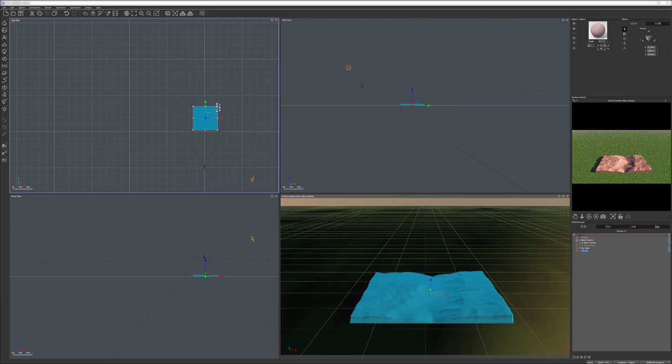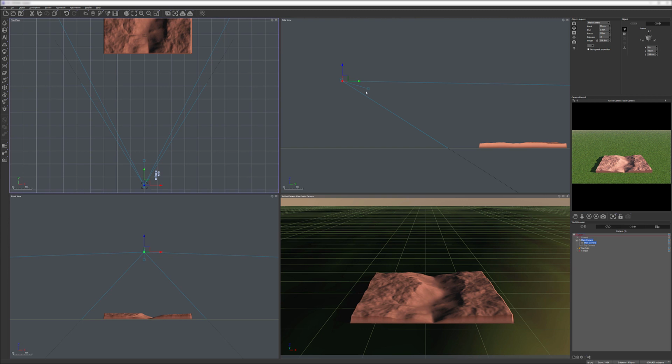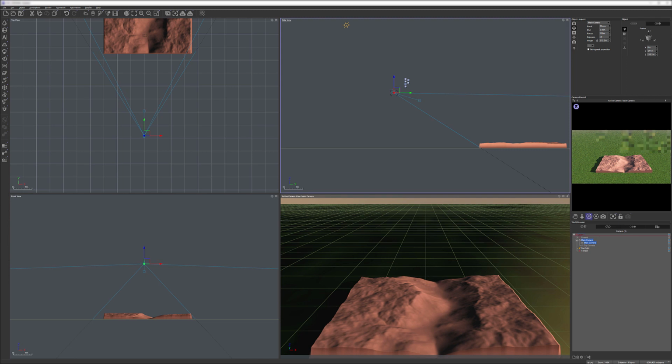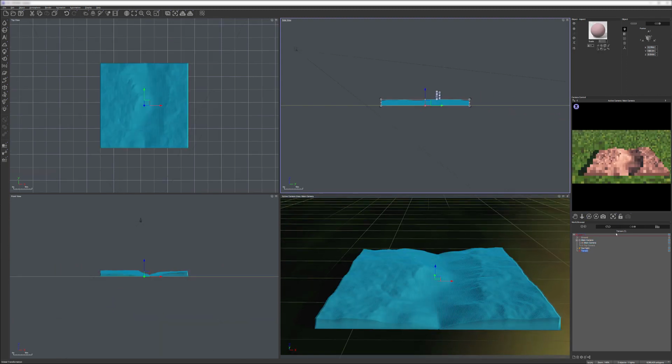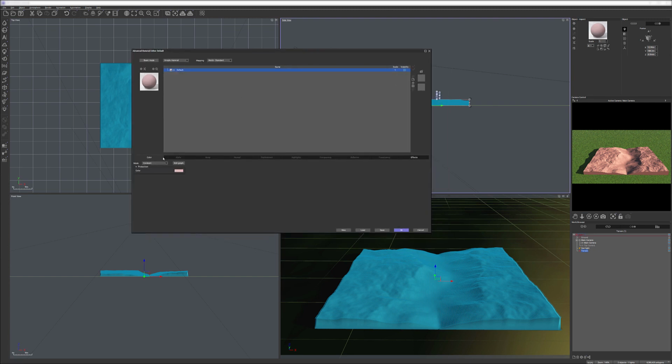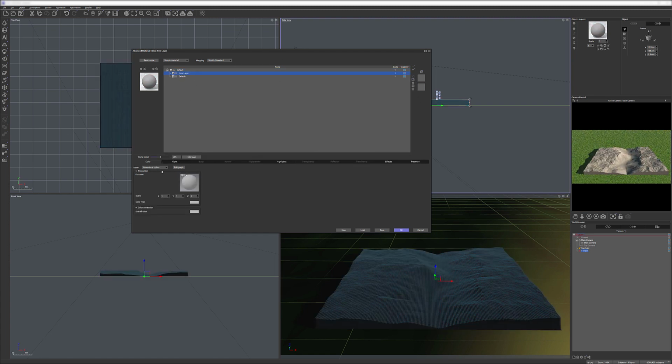Okay, right here we applied, and by default, you notice when we apply high field, it did use the mapping mode of procedural from the image, so it's by default. Okay, let's bring our camera just a little bit closer. There you go. Okay, let's go ahead and open the material editor for this terrain. So what's happening if I select and I want to create another material, put it on top of this. And as default, I'm going to just select one more material. And I'm going to select mapped picture.